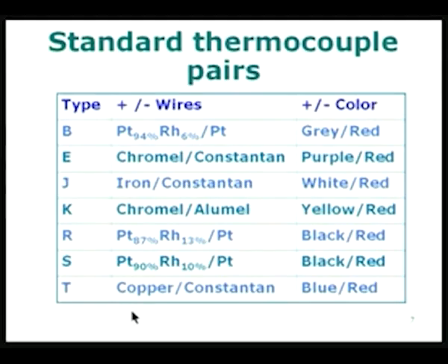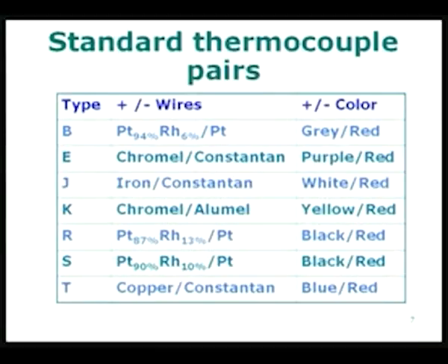This is always the problem. If some instrument has got a large range, usually it will be limited in some other sense, and in this case also you will see that it is a large range, but it is going to be less sensitive. Sensitive means the amount of voltage you get for a unit degree difference between the hot and cold junction, that is nothing but the Seebeck coefficient. Seebeck coefficient is very small for the platinum rhodium platinum thermocouple as compared to the E type.